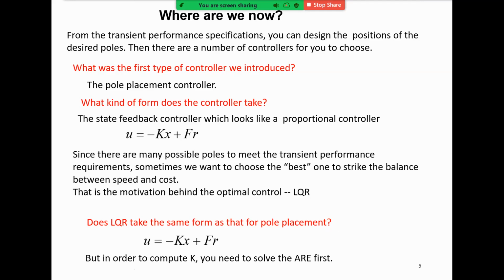For that final answer, you have to give me the whole calculation procedure. Like you say, okay, you are not going to solve this ARE equation directly, right? There are two ways. One is to do it directly. That one will not work out because this is a 6th order system. It's very complicated. You have to use the eigenvector method. You have to get a 12 by 12 matrix, and then, of course, you can get the eigenvectors. For those stable eigenvalues, you get those eigenvectors, put them together, and then use the formula to get the P matrix.